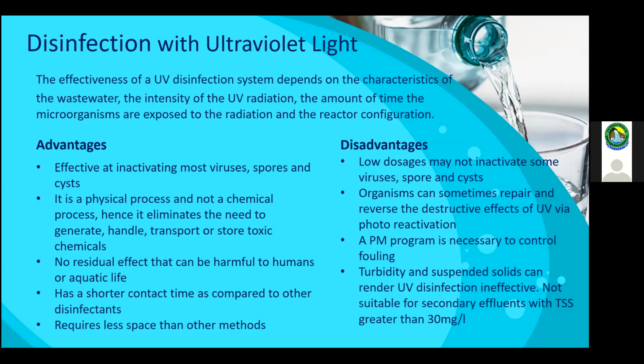Turbidity and suspended solids can render UV disinfection ineffective. UV disinfection is not suitable for secondary effluents and effluents with total suspended solids greater than 30 milligrams per liter. And with that is where I will end the presentation part and open the floor for any questions that you may have.